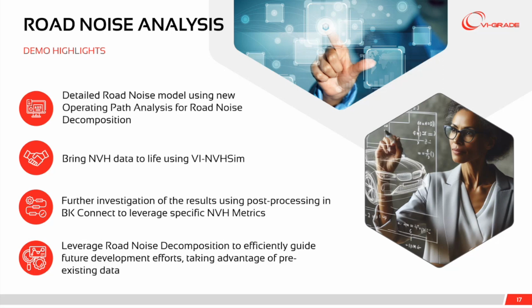And all of this really culminated in leveraging our road noise decomposition to efficiently guide our future development efforts. Perhaps if we need to go to the level of a TPA or SPC type analysis, we know now that the structure-borne is most important. And if we're focusing on the front or the rear, we know specifically some directions and maybe areas of the vehicle left to right that are most important for us. To be a little bit more specific, we don't have to worry about the airborne component, so that cuts down the complexity of doing further analysis. We know we can focus our efforts where it's most effective.